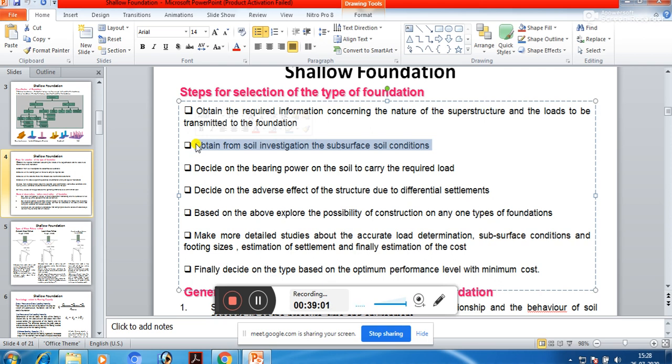So these are very important. So now you understand what is the relevance of soil mechanics with foundation. You need to do sieve analysis of soil. So you will have to collect the soil from the subsurface level where you are trying to construct the foundation and test the soil for different characteristics. Characteristics of strength you will have to test, characteristics of settlement you will have to test, other different characteristics like its water content, its different consistency limits, its permeability, everything you need to check. Otherwise you will not be able to give the proper idea about the selection of type of foundation.